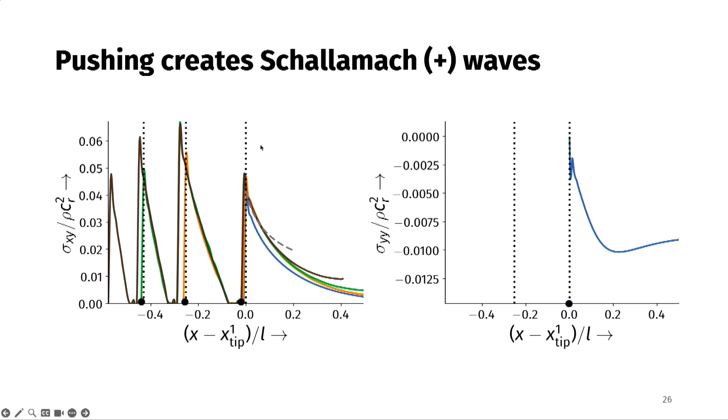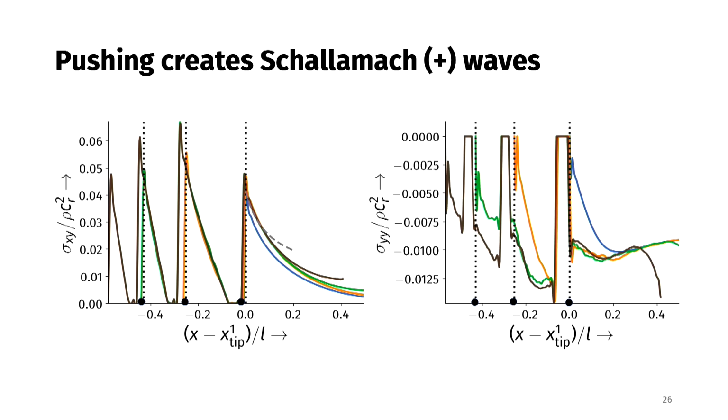We can look at sigma yy, which becomes much more interesting. This also seems to be singular. Again, this is a finite lattice, so you can't say if it goes to infinity or not. It won't, because of the finite distance between these bonds and the finite forces in the bonds. And again, if you look at it in the co-moving frame, the stress falls off. This region is 0 basically because it's behind the wave where it's detached, just like here. The stress initially was very high when the first wave nucleated, but after that, the normal stress is reasonably low and continues to be low. And the same thing happens with subsequent waves as well. Right? Good.